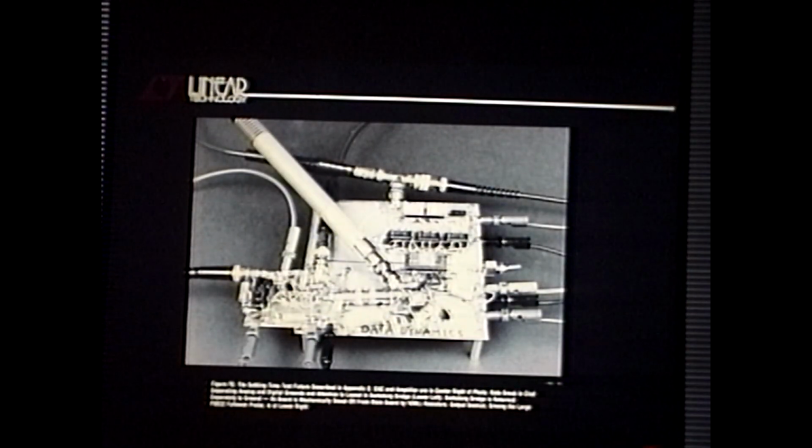Also, you'll notice, remember I talked about pulse generator and the 50 ohm termination. There's the 50 ohm pulse generator termination. I don't do the termination on the board. I don't dump a 5 volt pulse generator into 50 ohms and get 100 milliamps of ground current flowing around in here. I do the termination coaxially so that this ground pulse generator current flows through the cable, through the terminator, and back to the pulse generator. I never dump those currents into my ground system here.